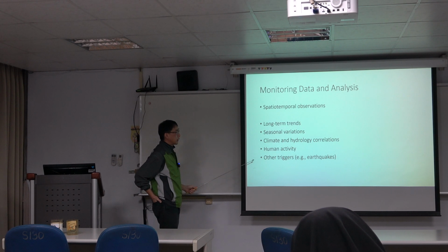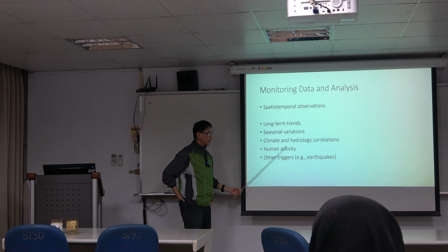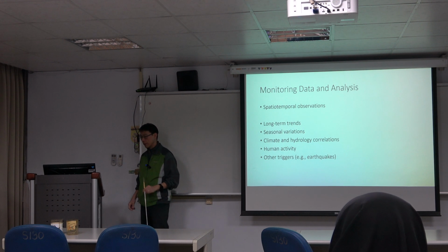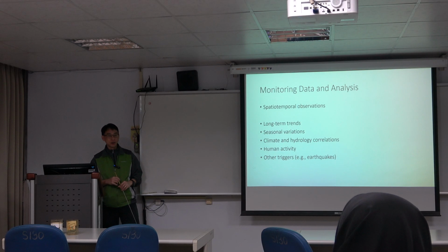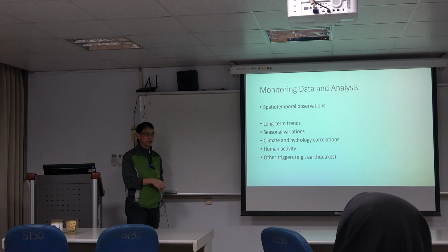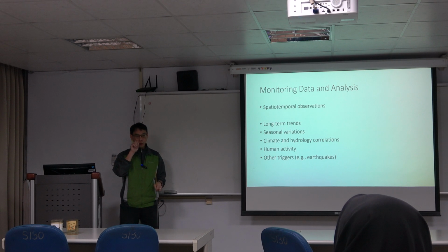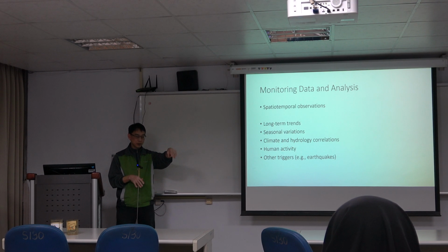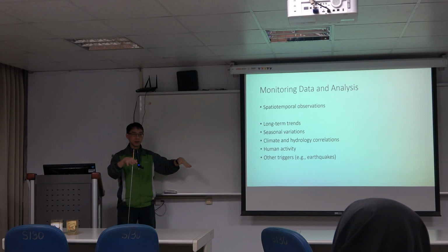Human activities can also affect it. For example, if you have agriculture nearby your observation systems, then the pumping affects your observations largely, and you are not able to assess the more natural background. We commonly put in groundwater observations to understand the natural variations of your system.